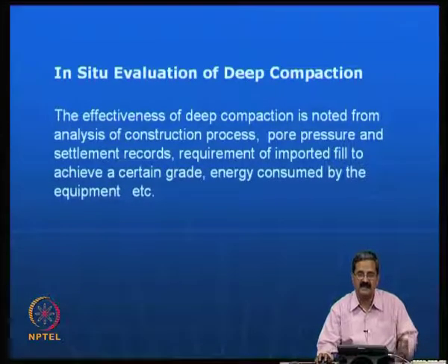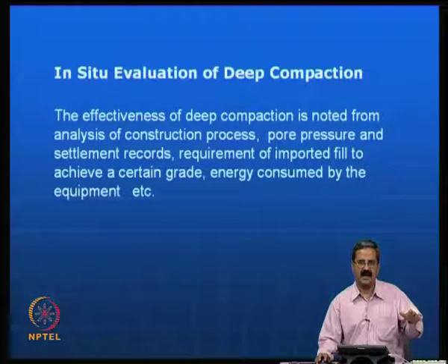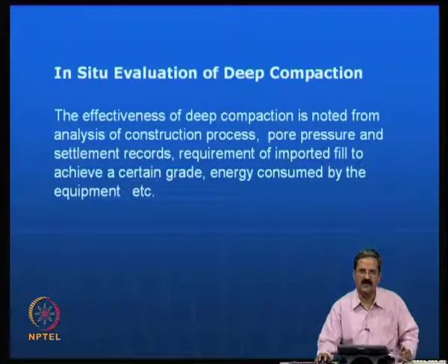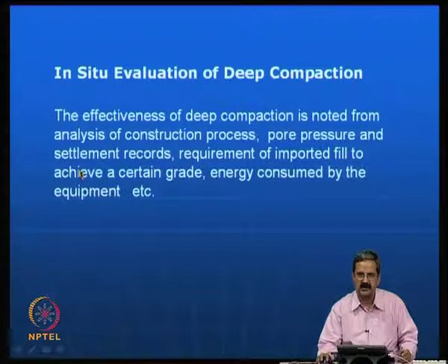And also, say for example, if there is a problem of noise because of the deep compaction, you can even go for smaller heights and closer spacing. One can always work out some sort of process wherein you can still get the effective improvement. The other important thing is pore pressure and settlement records, because pore pressures and settlements are very important. Finally, you may have initial settlements very high, but the final settlements need to be very, very low, that is subjective. You can only get that from settlement records and pore pressure records.